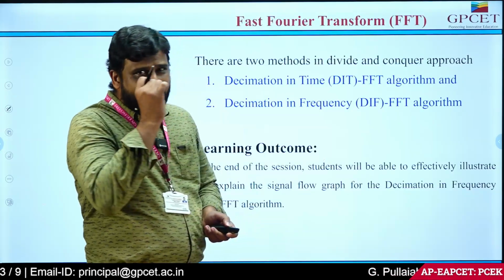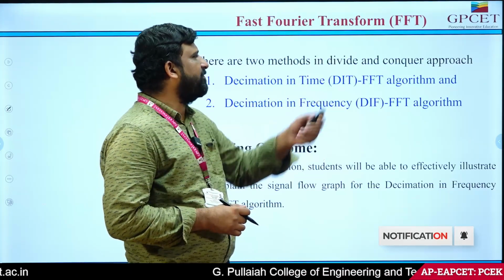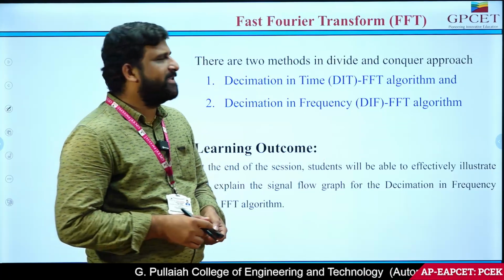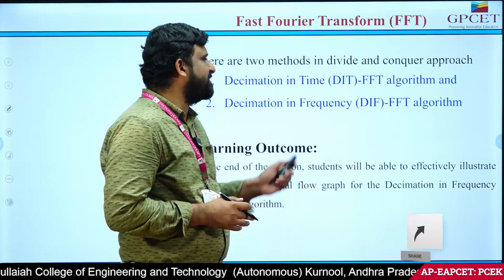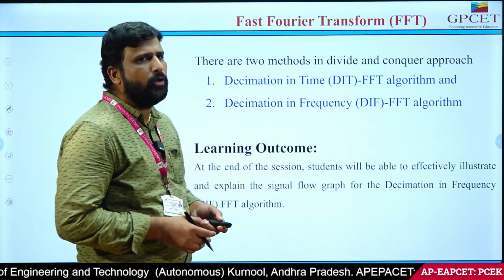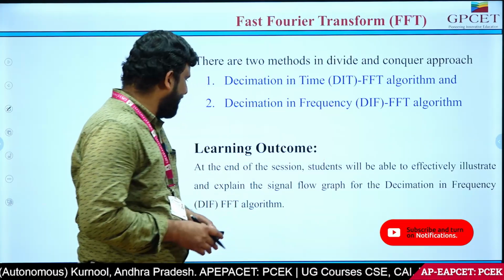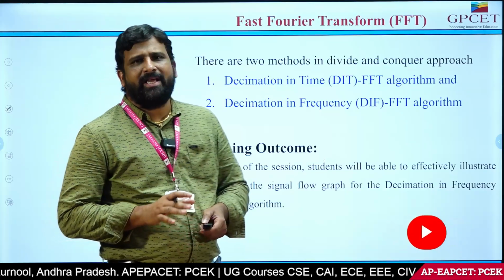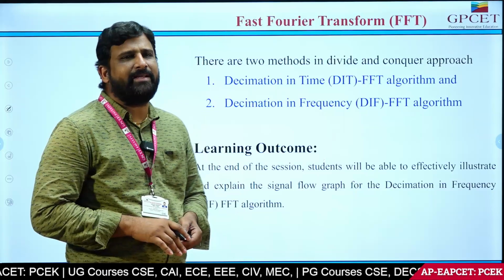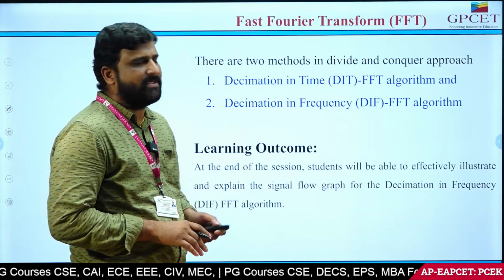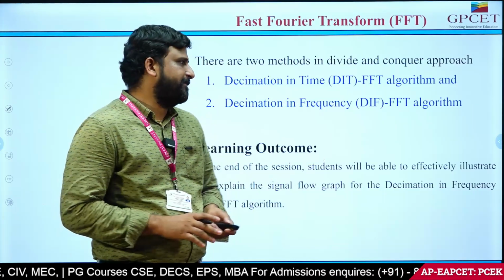In the previous lecture we discussed one method, which is the decimation in time FFT algorithm, and today we are going to study the same kind of algorithm, which is the decimation in frequency. At the end of this session the students will be able to effectively illustrate the example, and they should be able to draw the butterfly diagram related to the decimation in frequency. This should be the learning outcome after discussion of this topic.